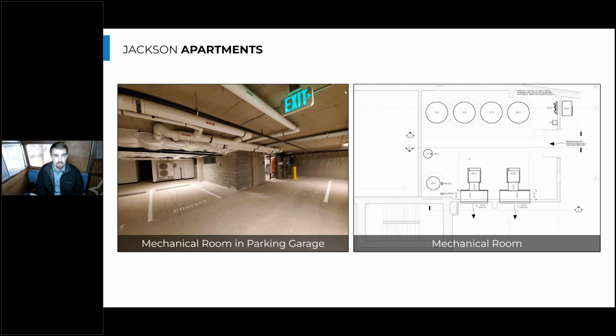So the cement in the garage is never below 40 or 50 degrees. By the time the air passes all the way through the garage and gets to the heat pumps, that air is going to be warmer than 40 degrees, which is the heat pump's minimum operating temperature in this situation. And then after the air passes through the heat pumps and that heat is extracted out of the air, it will continue out and then be sucked out of this garage exhaust that goes to the outdoors. So there's constantly fresh air circulating into the garage, warming up, being cooled down by the heat pumps as they extract that heat out, and then exhausted outside.